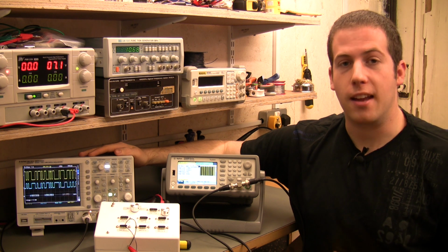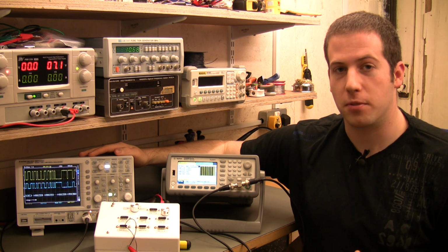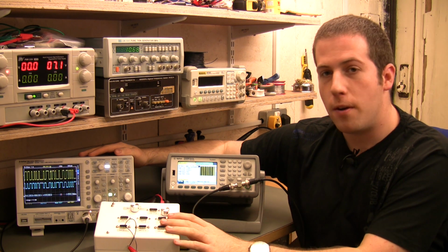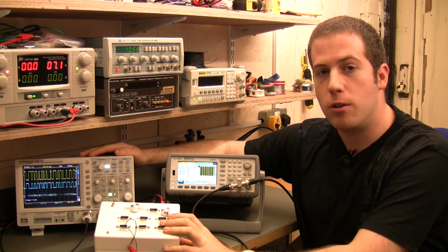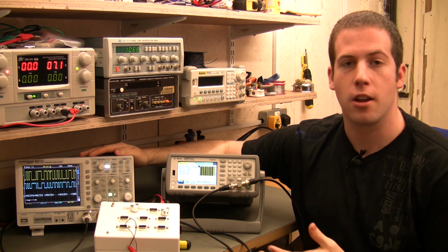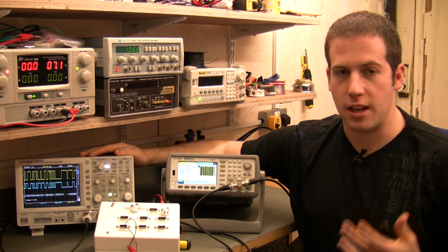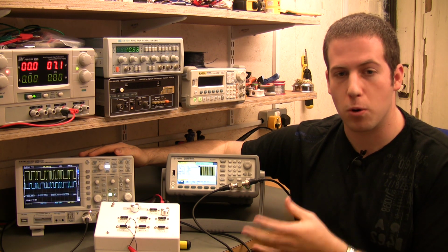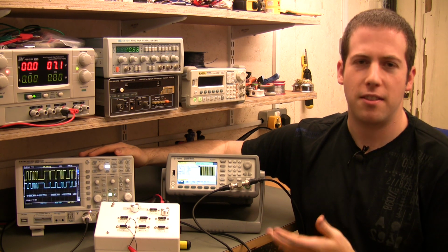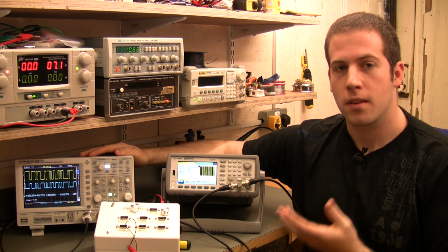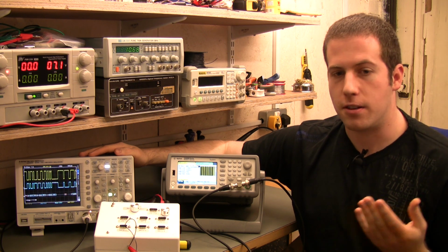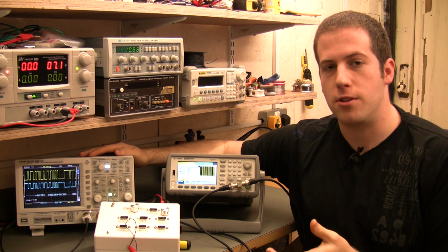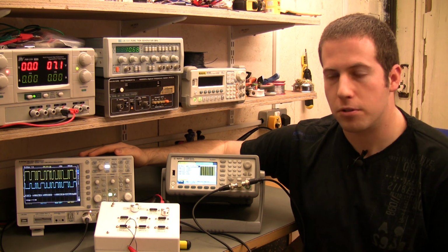So we talked before about being able to use the function generator to actually characterise the performance of circuits, and we're actually just going to give a quick practical example now. What we've got here is a bit of kit that we use to talk to microprocessors. So quite often, when you want to get a signal out for debugging or for test purposes, you send it out just as a raw serial signal, and normally this is going to be a 0 to 3.3 volt signal. Let's say you want to plug this into a PC or some bit of industrial test equipment. You're going to want that out at standard RS-232 levels, which is about plus minus 9 volts.